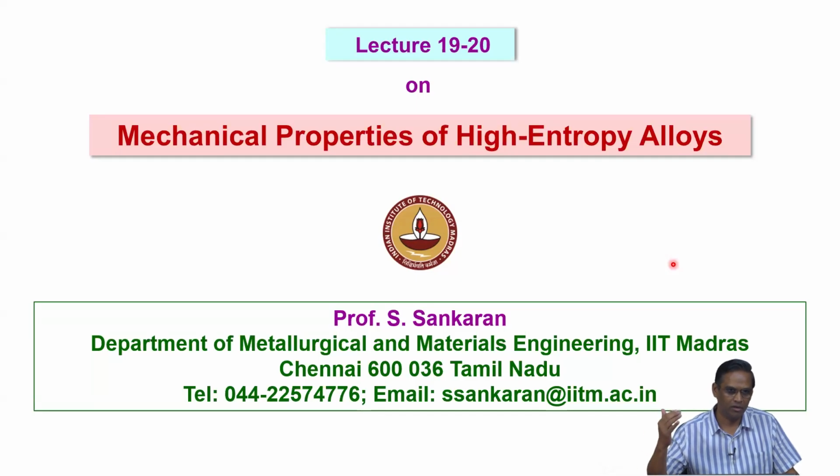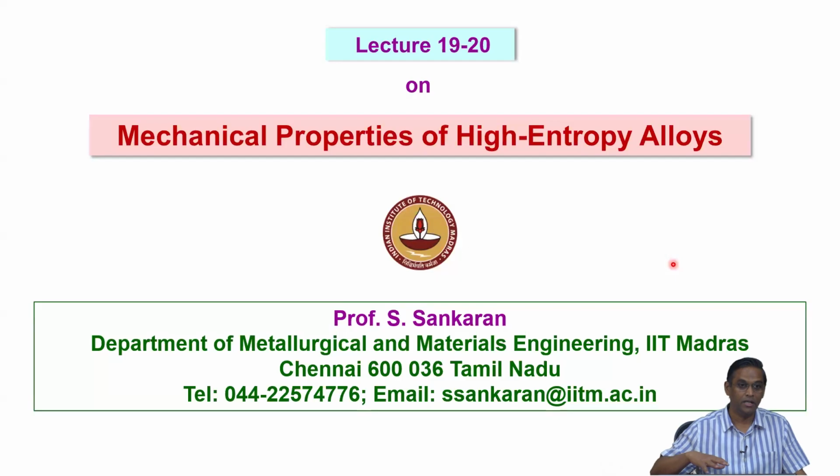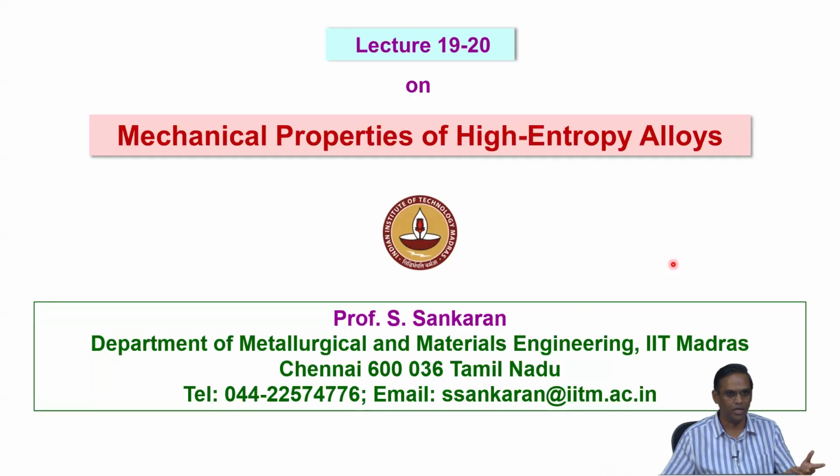But when you have the stacking fault energy which is low in a material, then your defect structure will try to rearrange only in a planar fashion. So you will have the planar array, where instead of looking at a cell structure which requires a kind of three-dimensional mobility of dislocations during plastic deformation, in a planar slip you try to form a network of dislocations, possibly a hexagonal network or a line of slip bands. So that means the three-dimensional mobility is restricted.